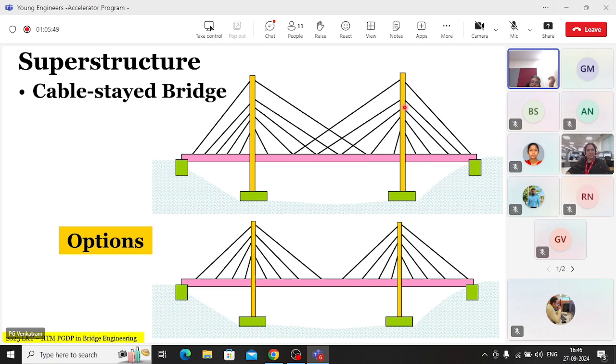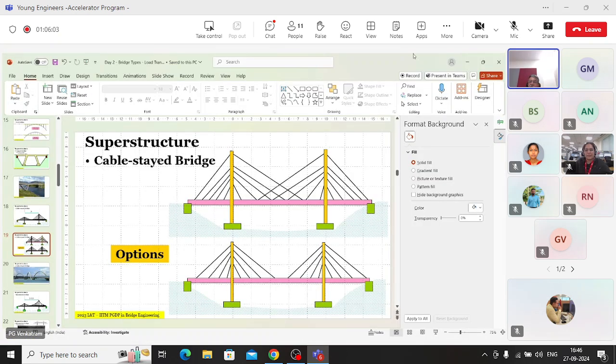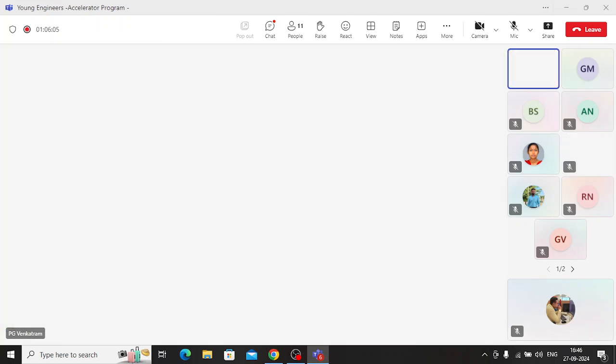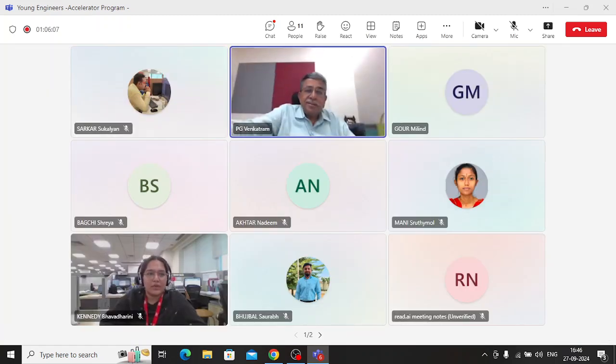Okay, there's another arrangement wherein these cables, when they are arranged at the pylon, have multiple different types of arrangement. One of the oldest forms was what is called a crossing cable, which were like this. If I were to show it to you again, as I told you, I can't see you and I have to come out of it. So they were crossing cables. That is how they were anchored in pylons, in some of the oldest cable stayed bridges. We may not do it now, but the earliest ones did. So they're crossing in the pylon, they can cross over.